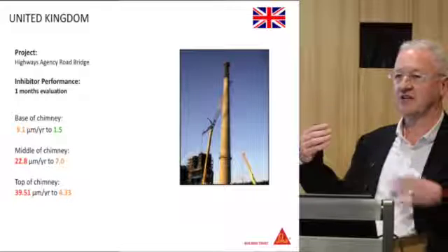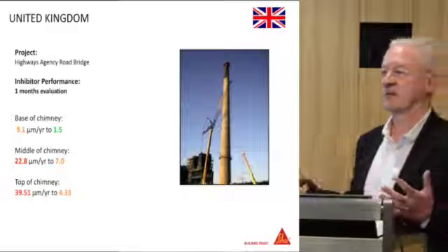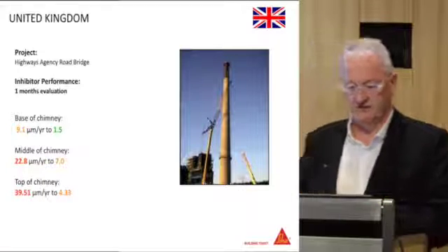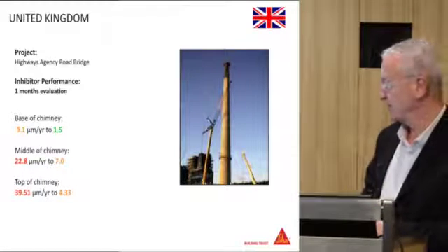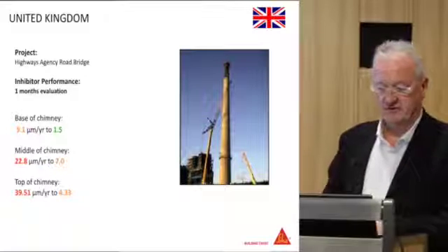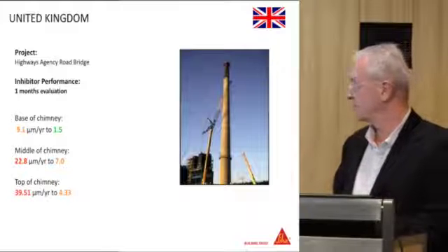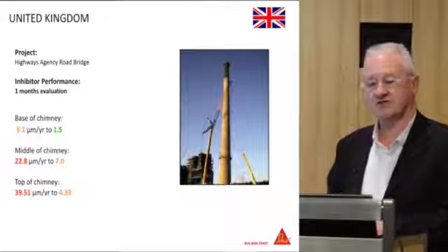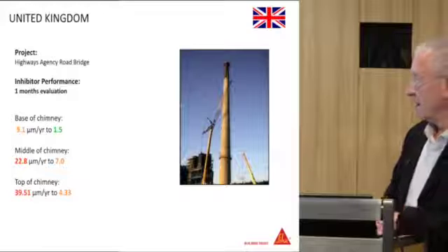As time goes on and you get more film around the reinforcement, you get greater suppression of corrosion. Middle of the chimney around 22.8 down to 7, and the top of the chimney, which you'd expect around about 39, down to 4.3 after one month. So again, fairly impressive results.